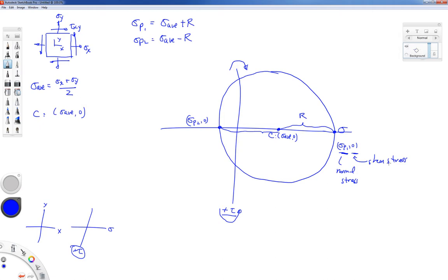Well, the Mohr circle shows that automatically to us. Now, the way to think about Mohr circle is not as two separate points that move independently of one another, but we want to think of an entire diameter at a time. Okay, so this red diameter that I'm sketching in represents the maximum principal stress state.